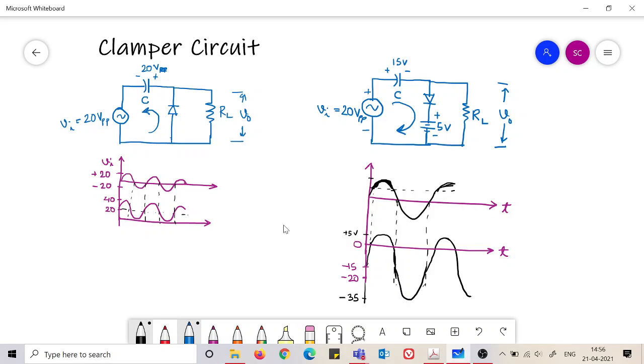When there is a capacitor in the circuit, you need to be careful, because the diode may not come to forward bias region for the remaining cycle of operation after the capacitor gets charged. So once the capacitor gets charged, the diode may not at all come to conducting stage anymore. Okay, and then you have to make it off for the remaining analysis and understand how the circuit is behaving after that. So this is what you should keep in mind.